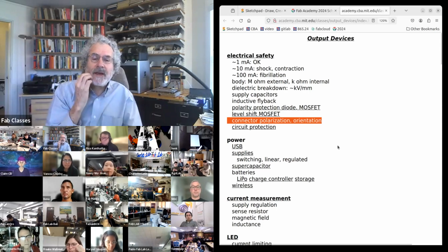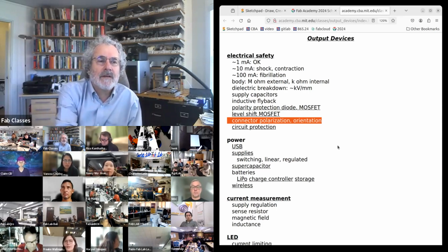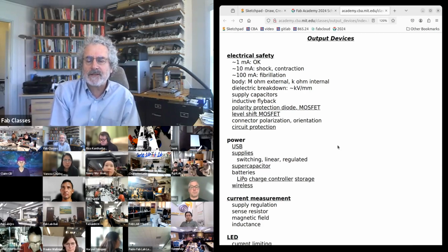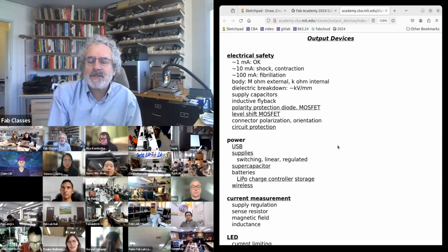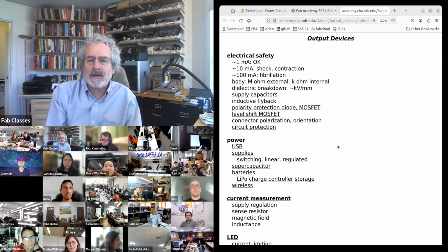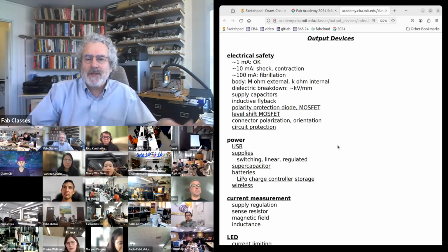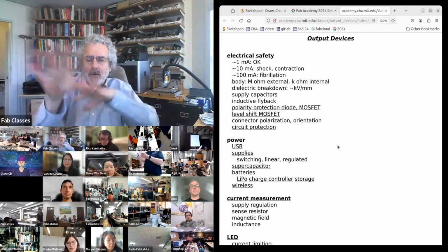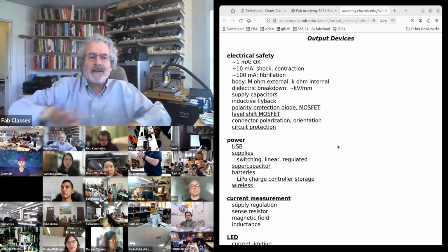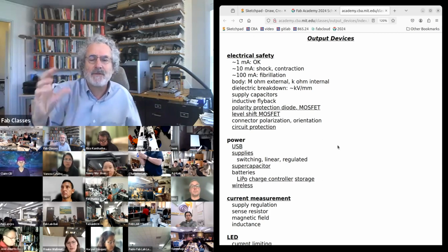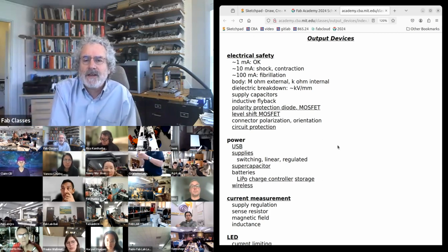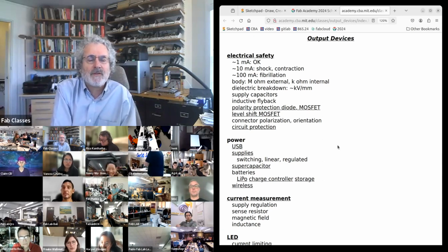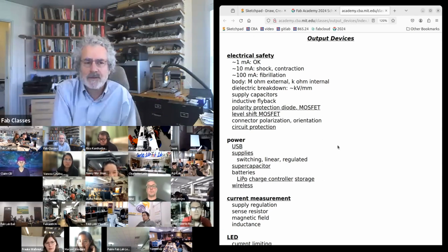So I would take away from that, dealing with power electronics is much like machining. You don't do it by yourself in the middle of the night when you're tired. Don't do it with too much coffee or too little coffee. You need to be relaxed, at peace. Don't do it, crucially, with a messy workspace where there's a whole tangle of wires. Be mentally clear, have a clean workspace. Be careful turning things on to be ready to turn them off. It's similar to the kind of precautions we take for machining, but when you're working with power electronics.